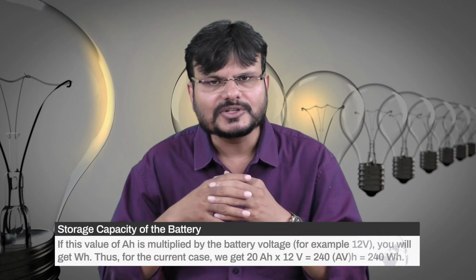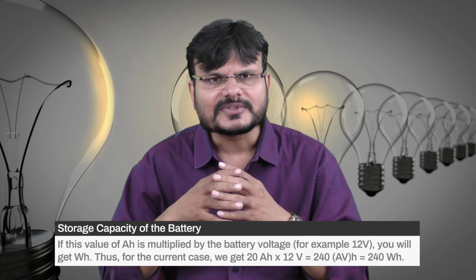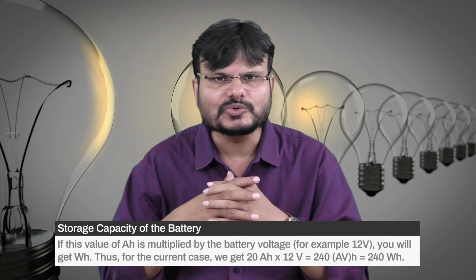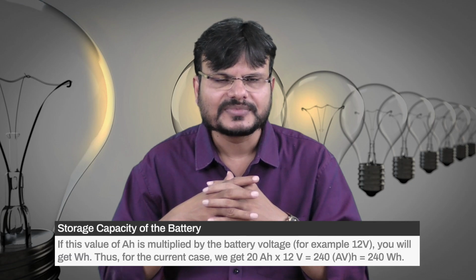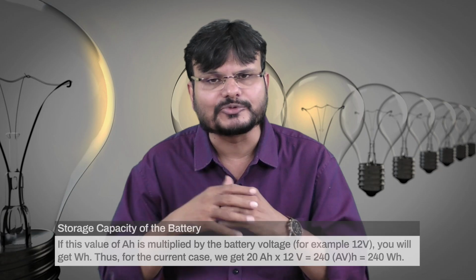If this value of ampere hour is multiplied by the battery voltage, for example 12 volt, you will get watt hour. Thus, in the current case, we get 20 ampere hour multiplied by 12 volt, that is 240 watt hour. This simply means that the battery is able to supply 240 watt for 1 hour, or 120 watt for 2 hours, or 80 watt for 3 hours.